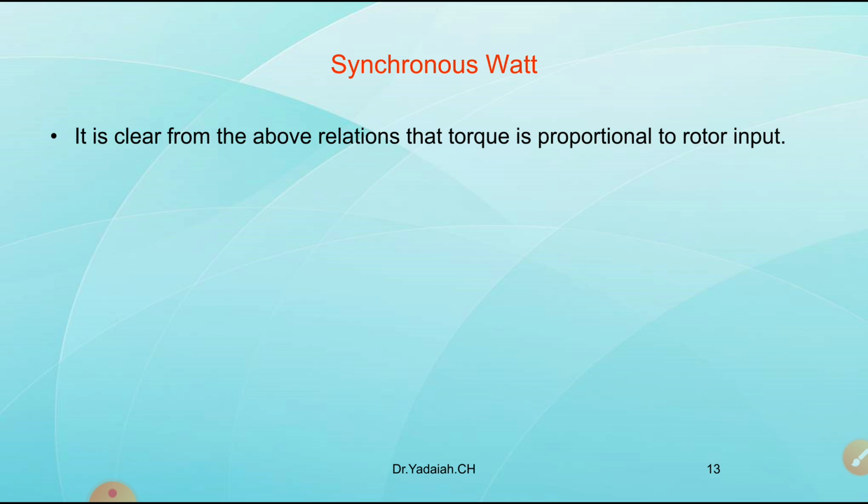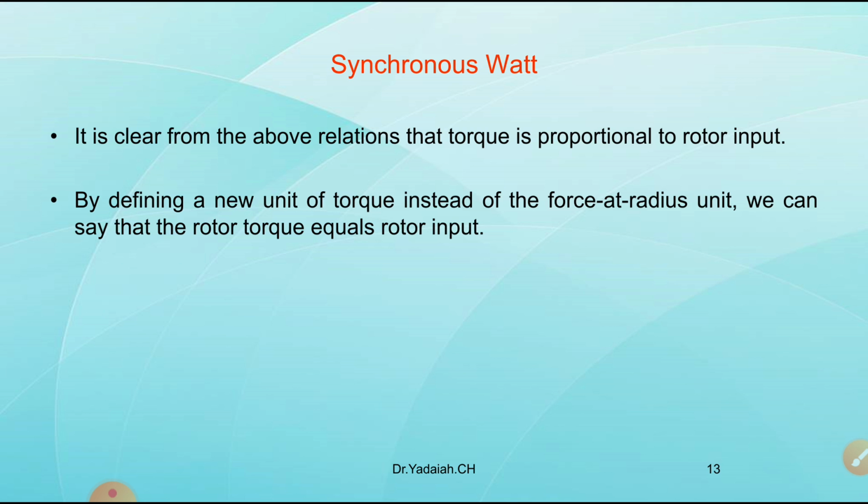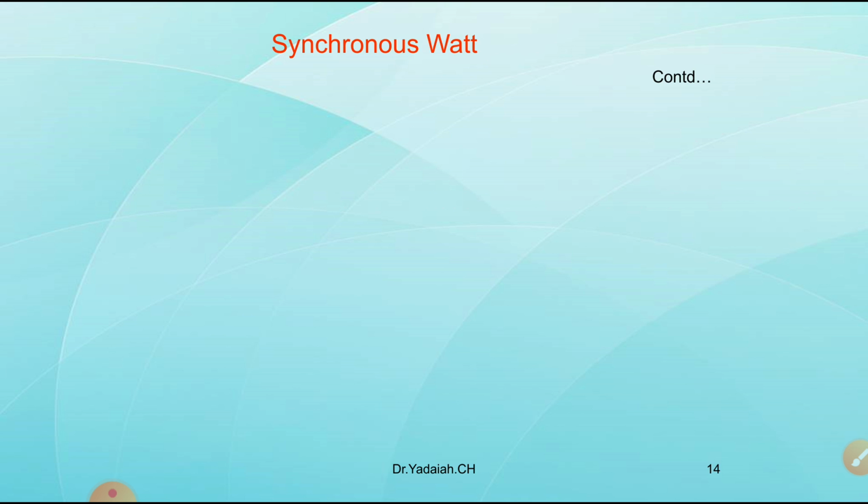Now, synchronous watt. What is the synchronous watt? Already we have explained the synchronous watt. That is the rotor input. We can say synchronous watt. It is clear from the above relation that the torque is proportional to the rotor input, that is P2. By defining a new unit of torque instead of force at a radius unit, we can say that rotor torque equals the rotor input. The new unit, the synchronous watt, is nothing but that.